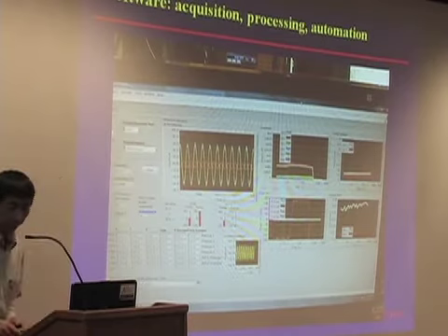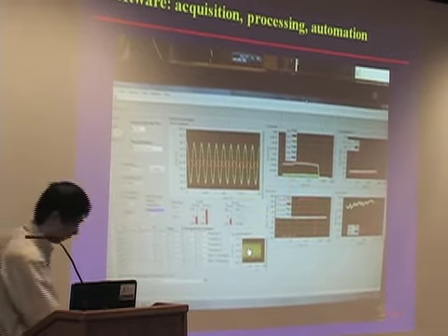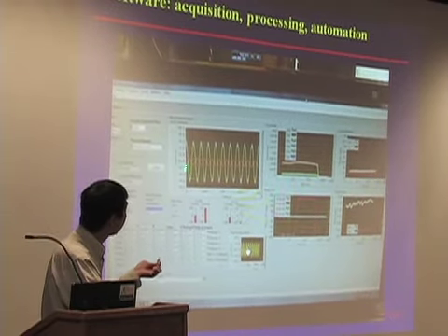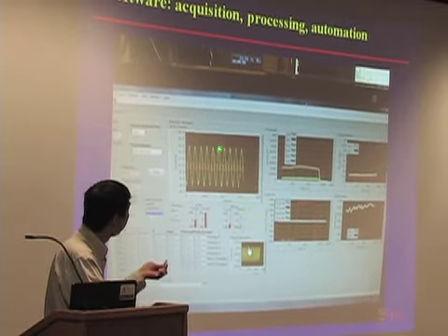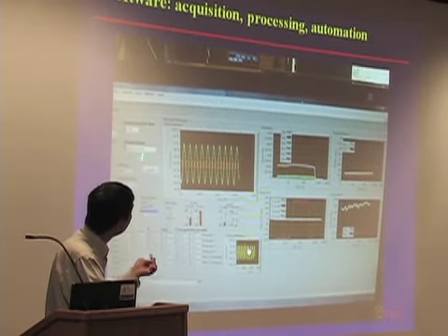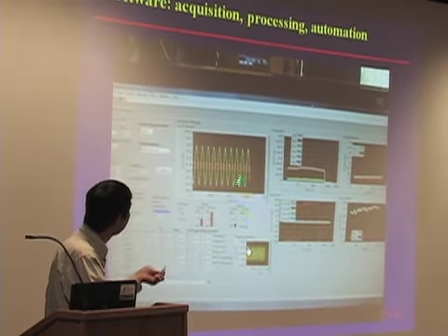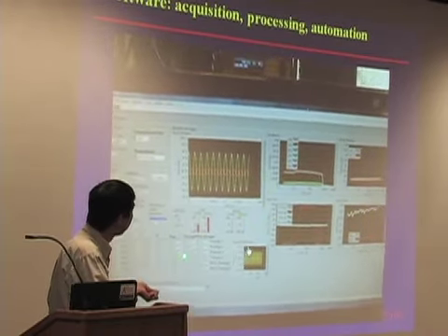I have a very, very short video here. We can show how it works. Here in the center, this is the monitor of the strain gauge output. We can see it's quite clear, quite stable sine output here. The blink here actually is changing the frequency because we have to scan from like 2 Hertz to 2000 Hertz. Every time it changes, these indicators just show the output in real time.